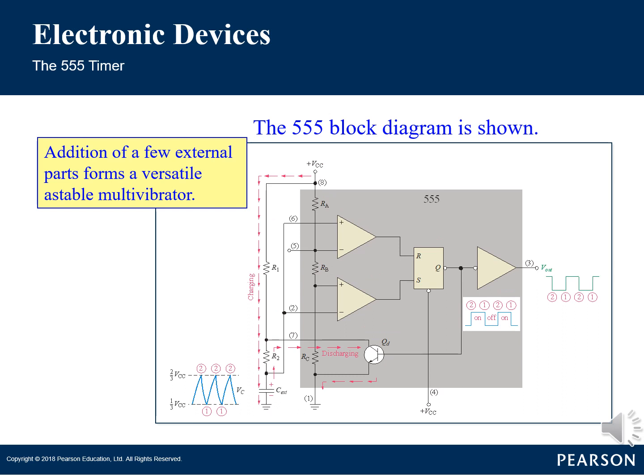The operation of a 555 timer oscillator can be explained by the charging and discharging of the capacitor. When power is applied to the circuit, the capacitor charges through the resistor. When the voltage across the capacitor reaches a certain threshold, the 555 timer triggers and the capacitor discharges through the 555 timer. This process repeats itself, creating an oscillating voltage across the capacitor. This figure shows the operation of the 555 timer in the astable mode oscillator.